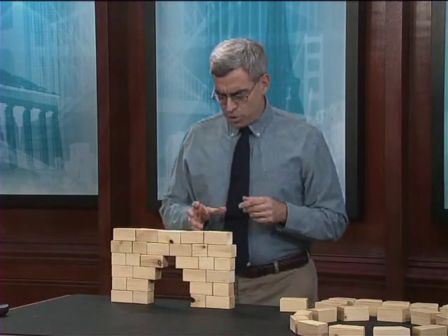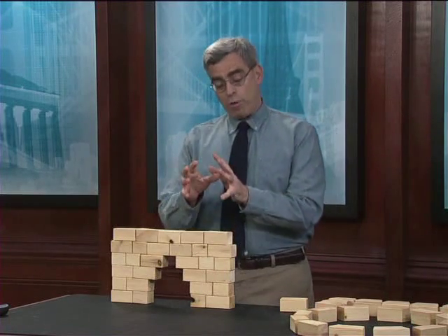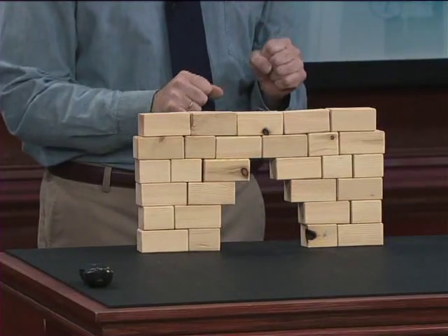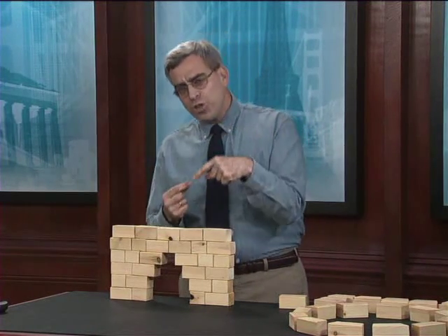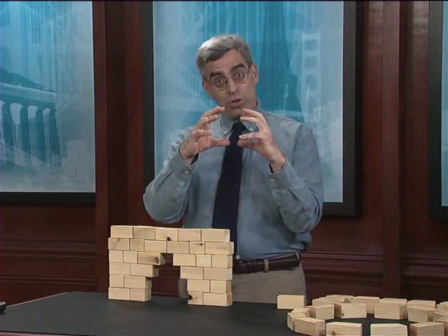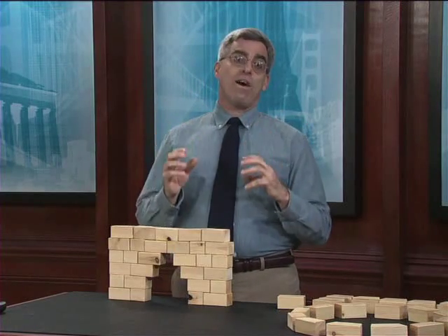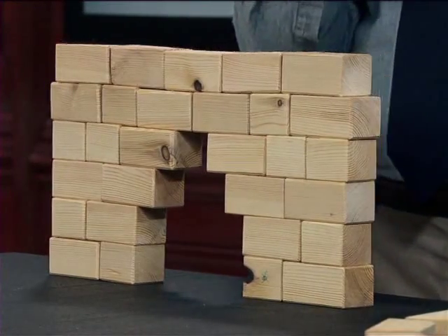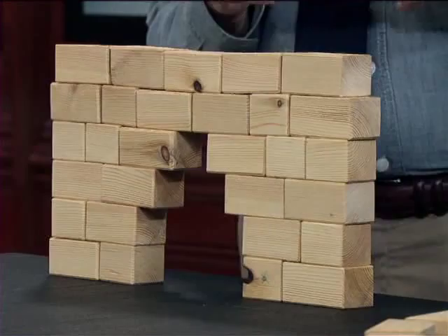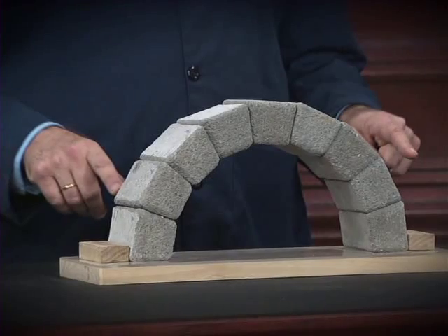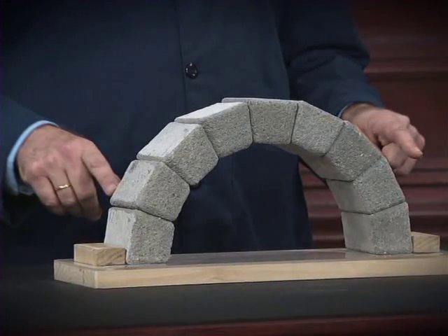A couple of things I'd like you to notice about the corbelled arch. Again, you can see the manner in which it was constructed through overlapping of each successive layer of stone. That overlap tells us something about the way the stone carries load. Each of those projecting stones is actually a cantilever beam. And because it's a cantilever beam projecting outward from its supports and therefore bending down a little bit, each of these individual stones actually must carry some amount of tension. And indeed, this is the key distinguishing feature between a corbelled arch and a true arch, the likes of which we saw a few lectures ago, because the voussoirs of a true arch are entirely in compression.